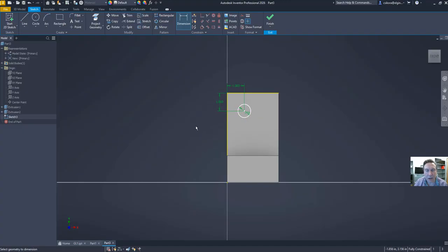So there we have it, now it's positioned. Notice with my colors that I have pre-selected here, the geometry turns white. White means, as you can see here, fully constrained. That's your goal. Inventor doesn't force you to constrain the objects with those dimensions, but especially for conceptualization, that's very useful. But ultimately, before it goes into production, make sure you get your things fully constrained, because that means you've positioned it with dimensions. There's no things floating around where they shouldn't be.